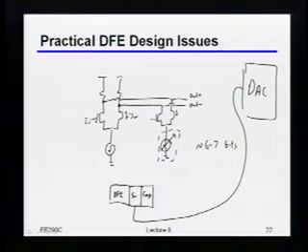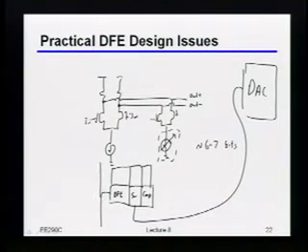It's just that you can imagine I maybe have another DFE nearby that I want to do. If I shove the DAC right next to the DFE itself, it'll eat into your pitch. It'll force everything to be spread apart, and then you'll be paying for really big wires in the front over there. So this kind of design, even though it looks really funny, where you have one circuit that's physically spread in like 3 different places, turns out there's usually a pretty good reason to do something like this.